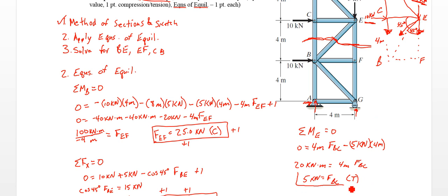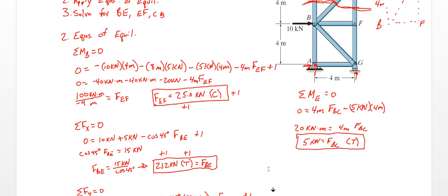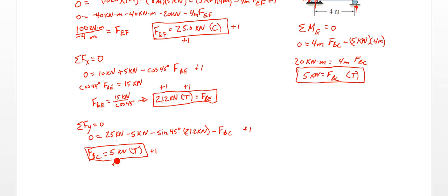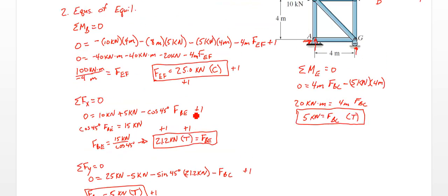And as a check, we did that independently of how we did it with the Y values. It's the same value, a little simpler method to do that, so we could do it that way as well. So whether you do it as another moment or as the sum of the Y forces, you get the same value.